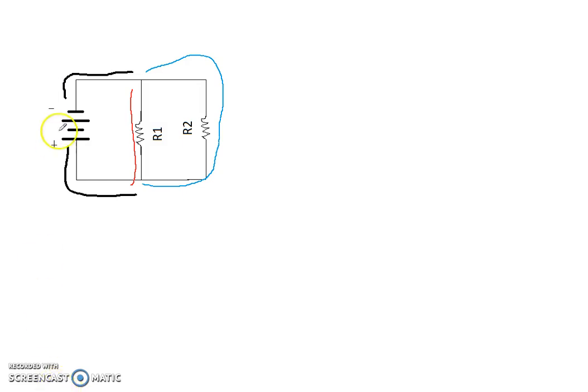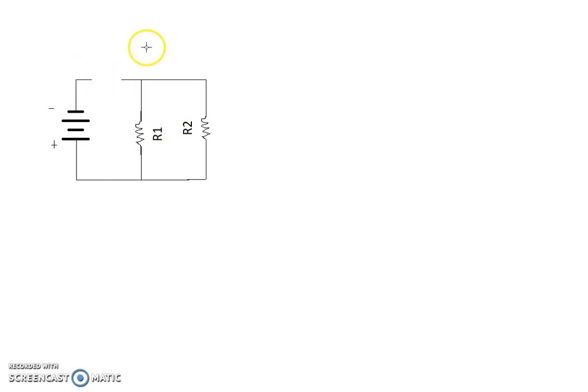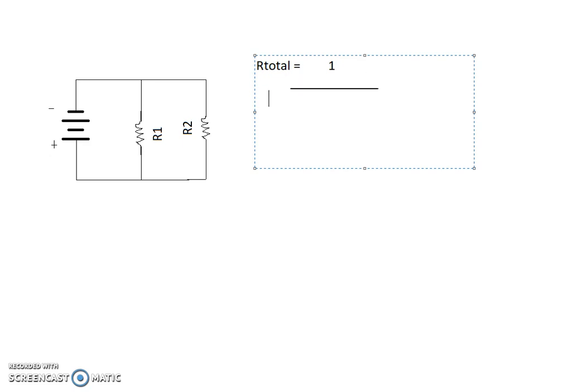So now we can actually move from just a parallel circuit, and we can get a little bit more complex here. Incidentally, before we go on to that, you're asking, hey, what is the R total for this? Well, I try to avoid overwhelming you, but it's basically 1 divided by a nice little fraction: 1 over R1 plus 1 over R2 plus 1 over however many R's you actually end up having.